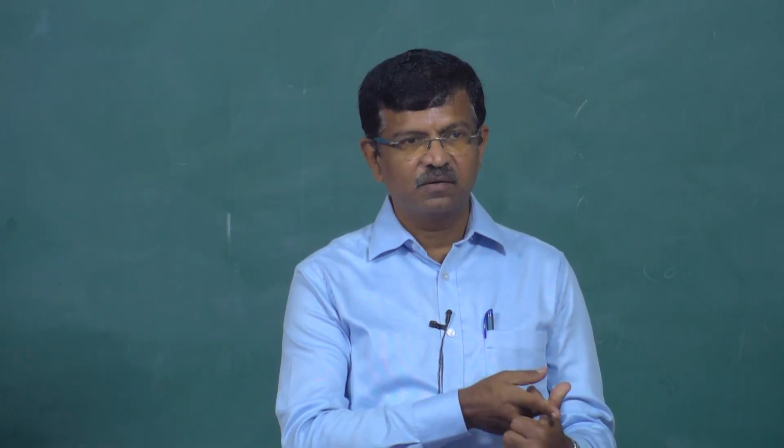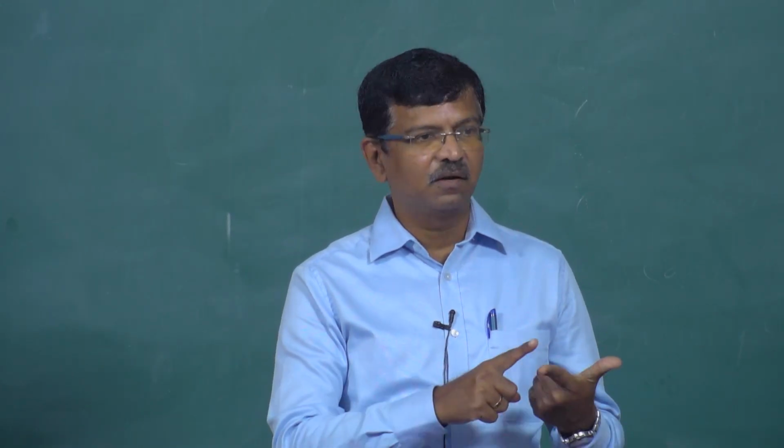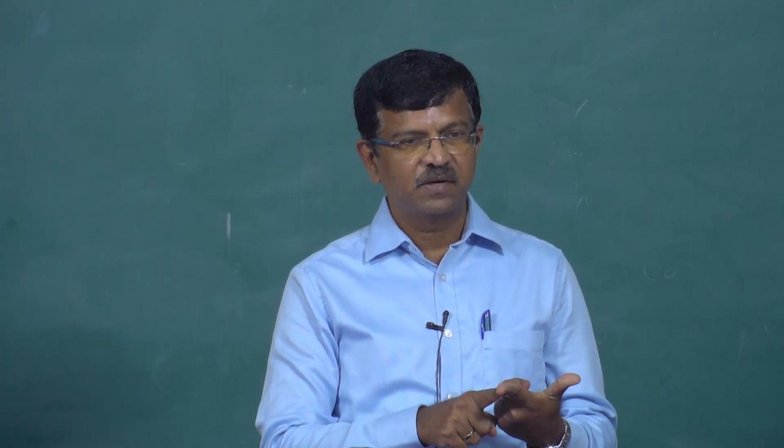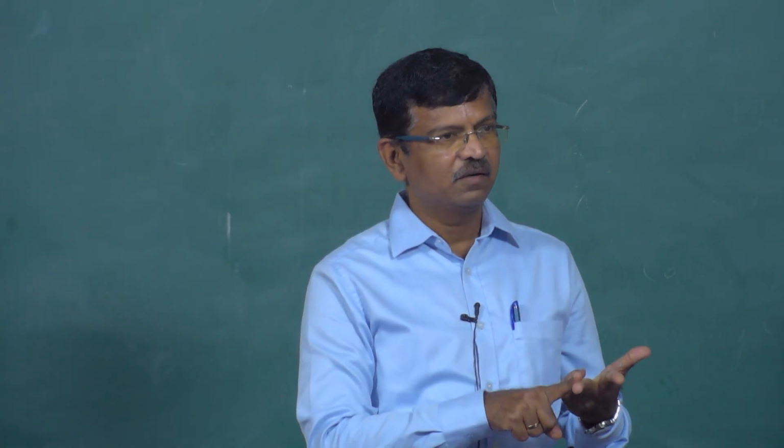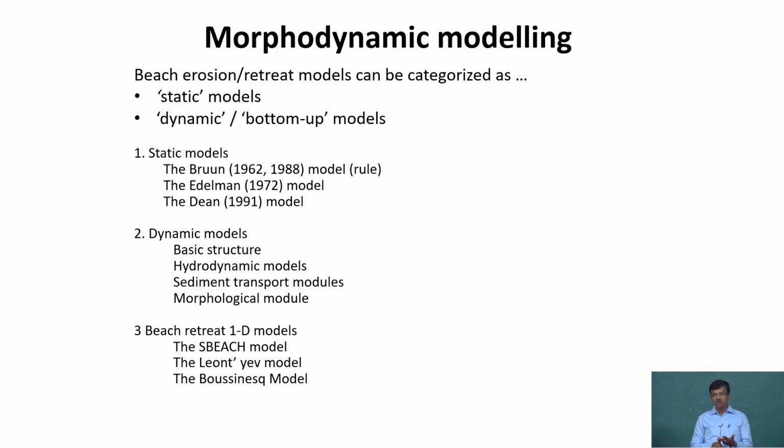We run the wave model, we run the hydrodynamic model, get all the driving forces in terms of the particle velocity or in terms of the radiation stress, then add, over and above, the bed load transport model, then suspended load by default we can use advection. That is a sediment transport module, and over and above that, finally we end up with the final coastal morphology we can predict in the dynamic model, which is systematic from the first to the end.